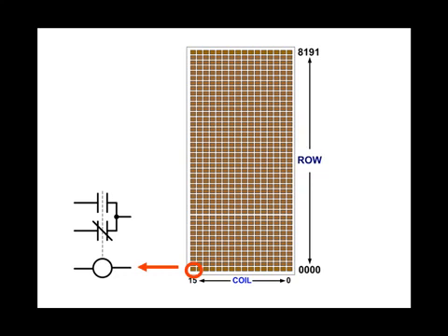One major disadvantage to using relays for logical control is that each contact can only be used once in a logical statement. If you need to check the state of a relay in more than one logical statement, you need to add more sets of contacts to the relay. However, keep in mind that there's a limit to how many contact blocks you can add to a relay. Each contact block has its own spring, and a relay coil only has so much force to overcome these springs, and each contact block adds more springs that have to be overcome.